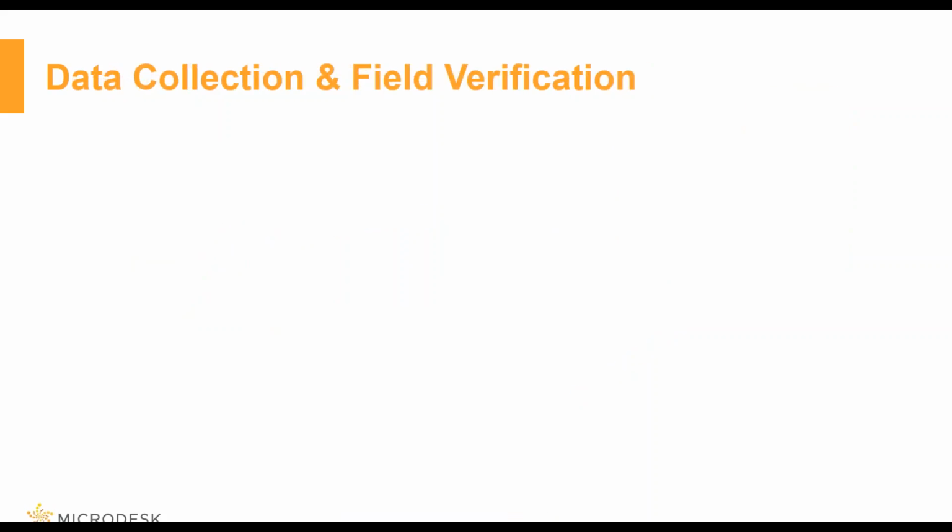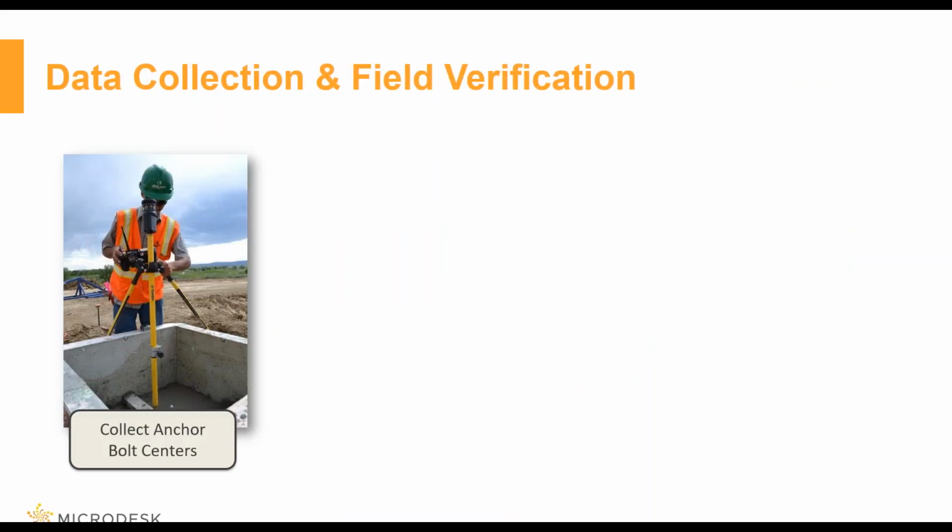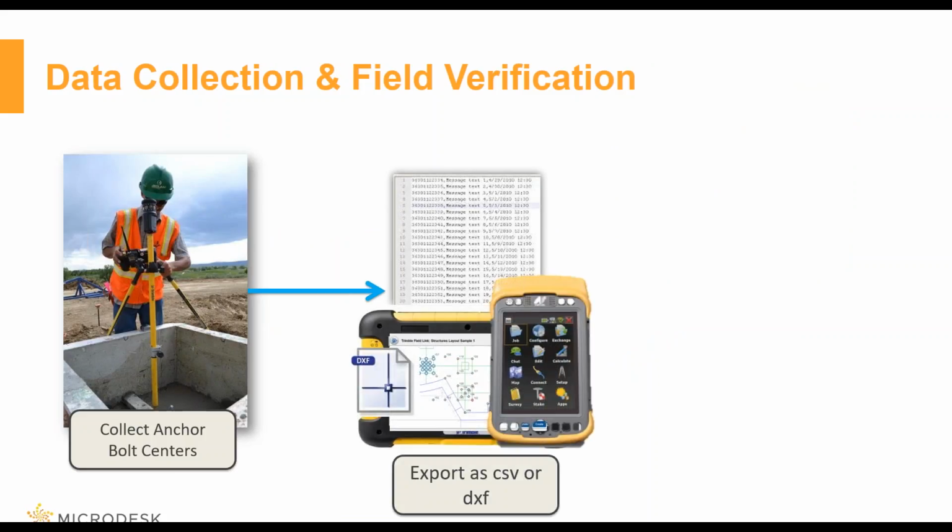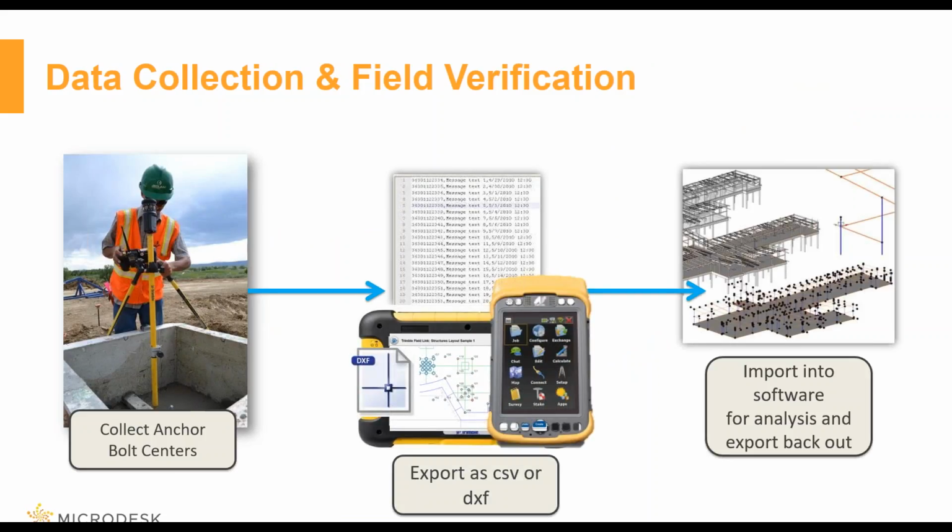Now another option, let's say we're going in the other way. Somebody out in the field is actually using the laser tools to actually collect the locations. And they're going to send that from that tool into the authoring tools, or even into the review tools like Navisworks. So that way I can check and say, okay, well, these are the points that they collected out there. Are they okay? Are they in the right spot?